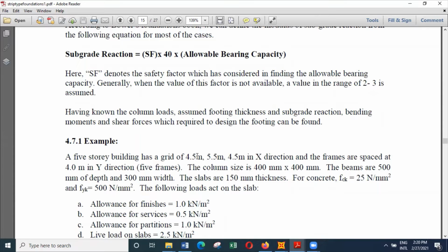And in this reinforcement, there are 3 types, type A, type B, and type C. Type A has less ductility, whereas type B has higher ductility. And what is manufactured and sold in Sri Lanka is type B, which has higher ductility than type A reinforcement.